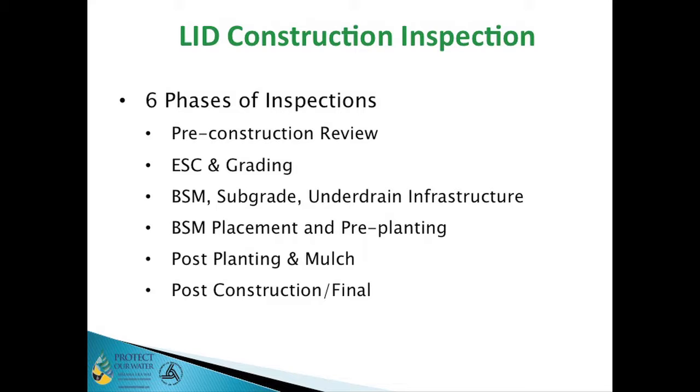At inspections during establishment of erosion and sediment control and grading, again, we make sure we're protecting the features that we're going to build. When we bring the bioremediation soil mix in, and the subgrade, and a lot of these features have, like, perforated pipe underdrains in them, getting all that in place, we need to do inspections and photograph it before we bury it so we know what was done and that it was done right.